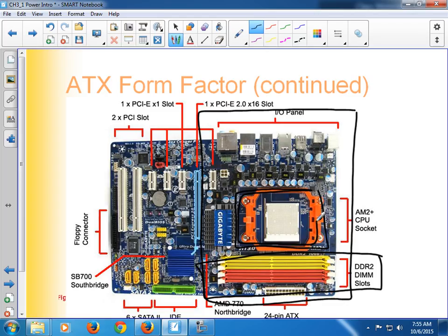the CPU goes. And then I've got these back panel or input-output panel connectors, and those are all different depending on the kind of motherboard I have. Okay, that's part of the motherboard when I choose it, but it's basically, because it's ATX form factor, it fits to a certain size and shape here in the back, and then I get this back panel that goes in my case that matches up with this motherboard.